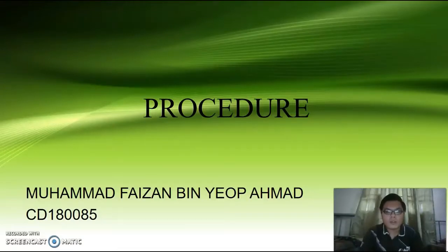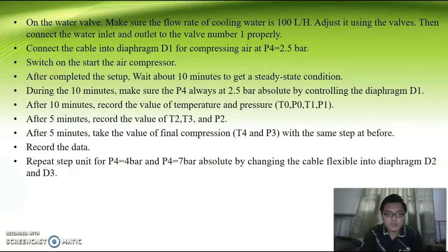I will present about the procedure of this experiment. On the water valve, make sure the flow rate of cooling water is 100 L/H. Adjust it using the valve, then connect the water inlet and outlet to valve number 1 properly.